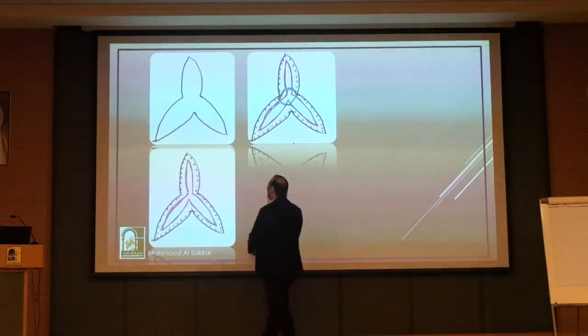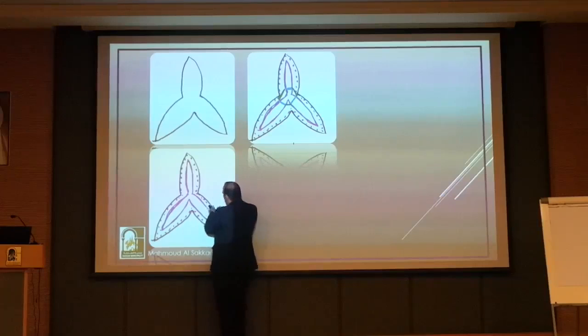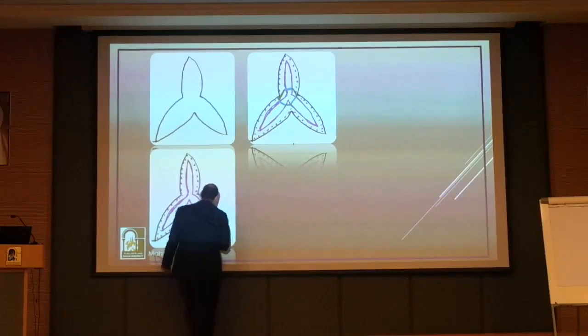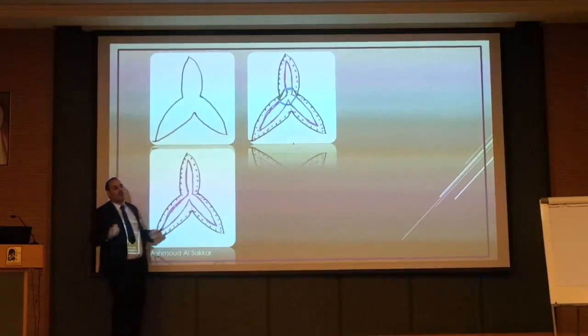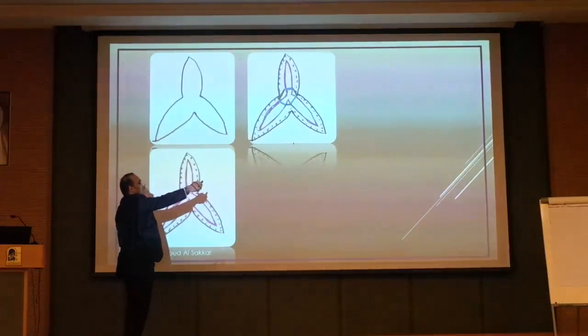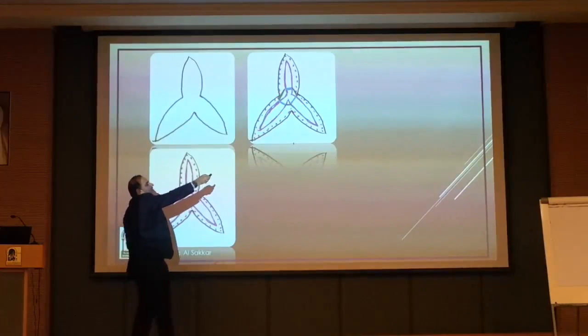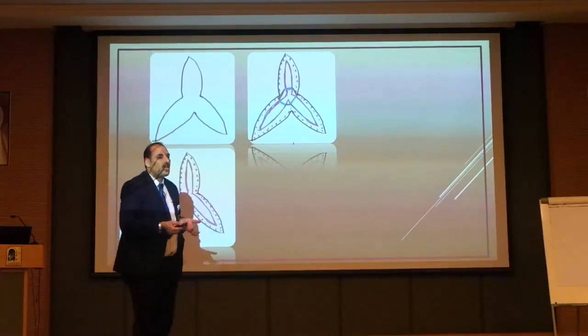Why? Because this system cannot carry torsion. Torsion is something like tension from here, tension here, or let's say compression. There is no resistance to torsion. What should I do? I'm going to make an internal core, hexagon shape or pentagon or octagon shape, to resist this torsion.